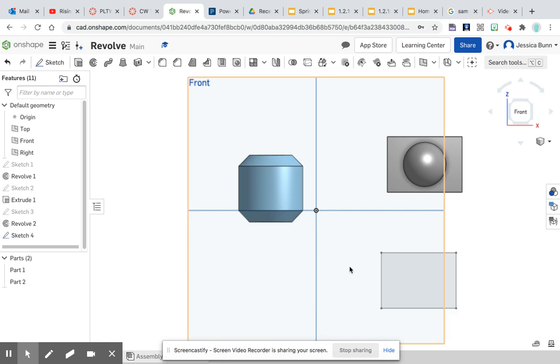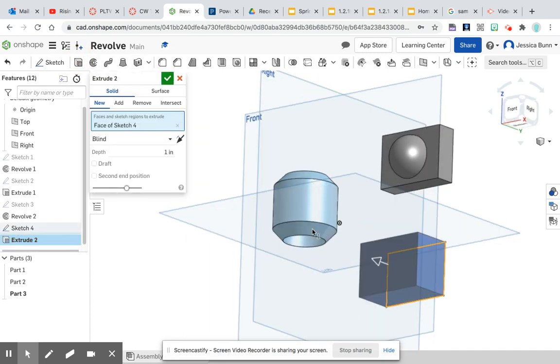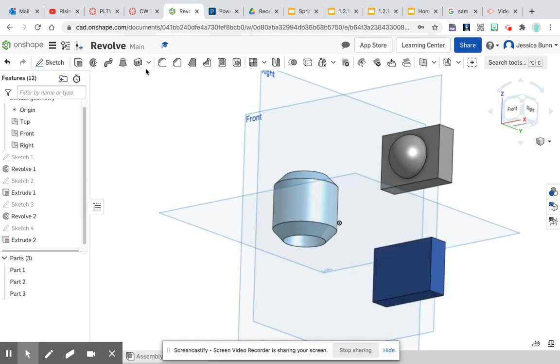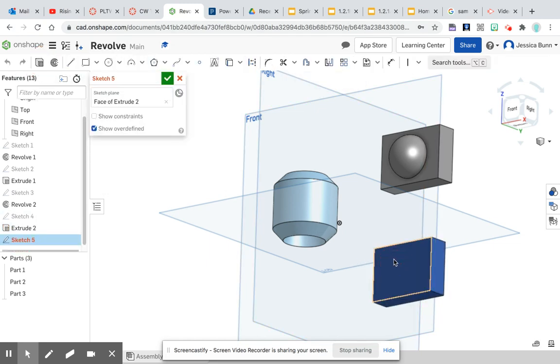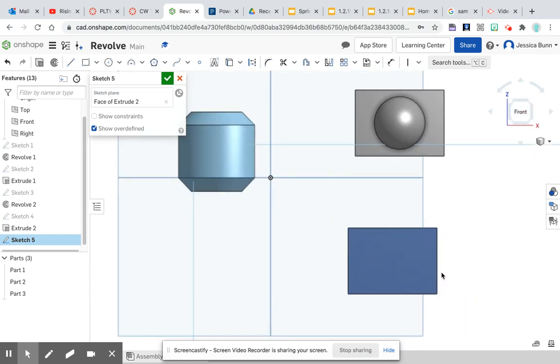Finish that sketch, rotate and extrude it at a distance of 0.5, and then click your green check. We'll start a sketch on the top of it and then rotate using the navigation cube. We want a line that has a distance of 1.